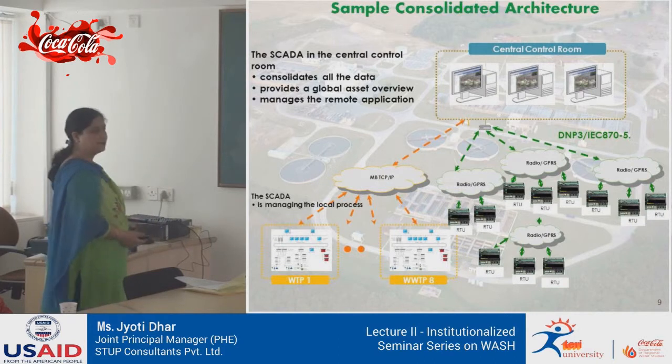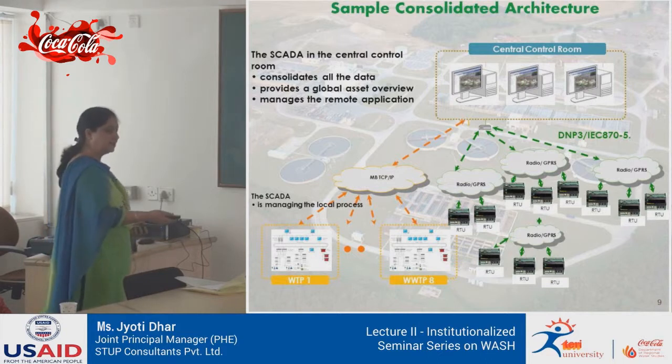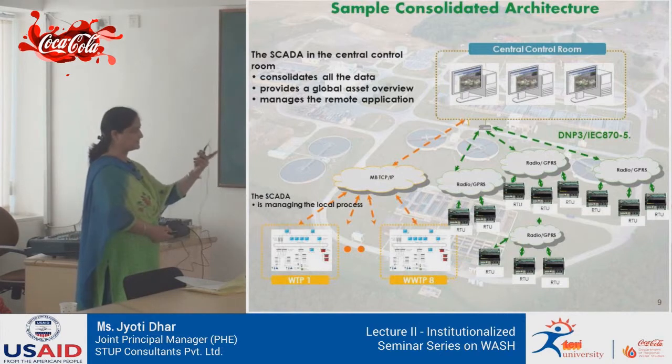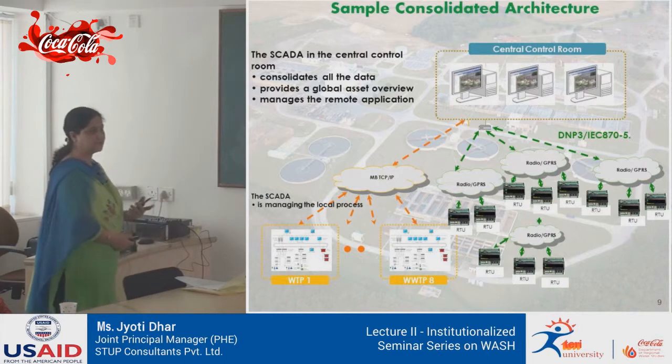Then you have these RTUs which work on the GPRS system or GSM system. Similarly, like you have a SIM on your mobiles, these RTUs have a SIM card wherein they work on a GPRS or GSM system. Even you can have a radio frequency system nowadays, or satellite. Via satellite we can also communicate the data.